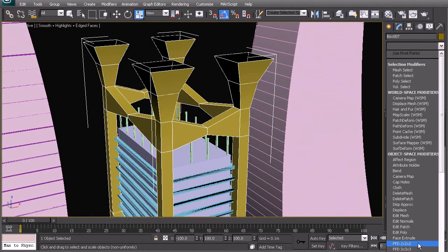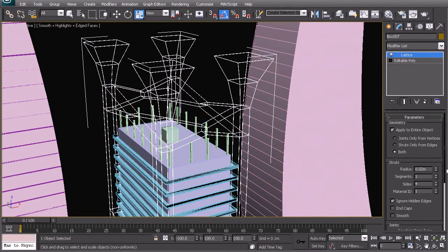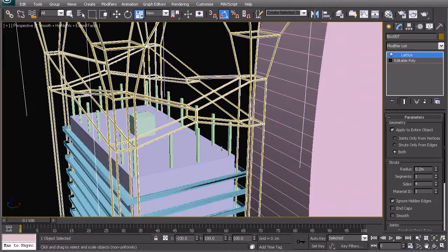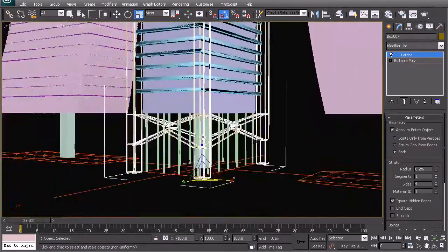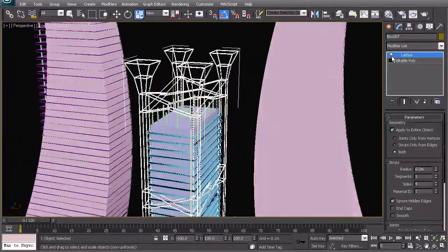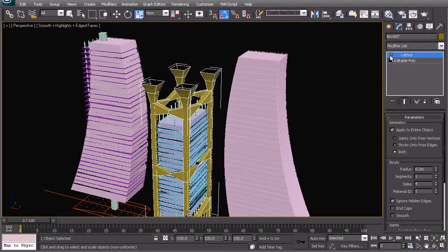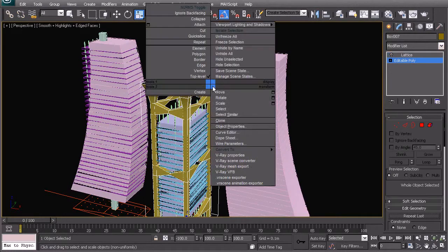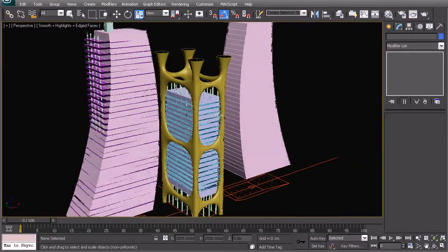So what you would do in that case is you could say, okay, fine, I undo my NURMS and I'm now going to add a lattice to this. So press LAT, press enter, and now we have a lattice shape happening. We can change that radius up to, let's say, 0.2 to make it quite thick, and we see now that we have sort of a steel lattice form coming up, and this is all just in a couple of clicks, and you can show different conceptual examples using this method without really going through the trouble of remodeling things 20 times. So this way we can have quite rapid turnaround times for different options. Right there, we went from something very organic to something very structural and engineer-like.